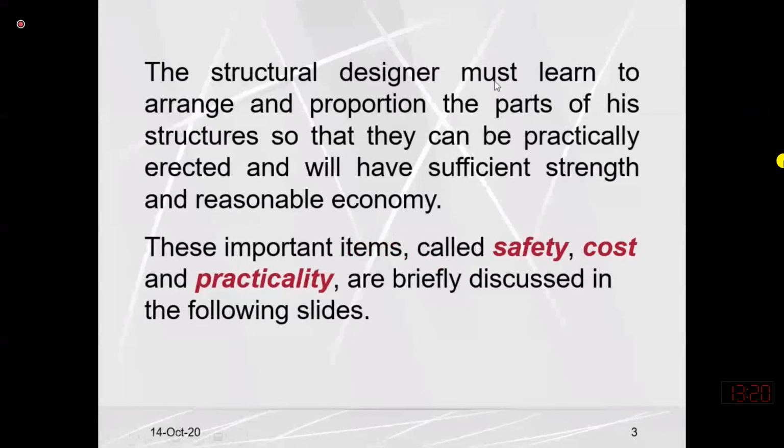A structural designer must learn to arrange and proportion the parts of his structure so that they can be practically erected and will have sufficient strength and reasonable economy. So we have to proportion. Proportion means that I cannot use a beam of very large length. Maybe you can say I can design it even though it is a tension member, because in tension member design it will not buckle. We will see this in our tension member design.